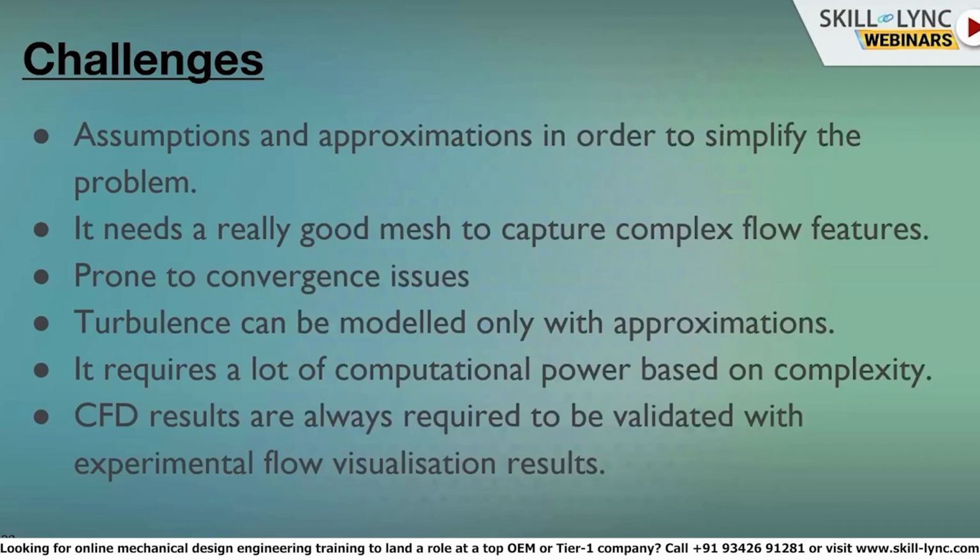Nowadays a lot of variations are coming: different turbulence models, different wall functions, different numerical schemes. You might be trying to solve a complex phenomenon using complex schemes, and then you will end up with a convergence issue. Then you may need to fine tune the model and get it right.